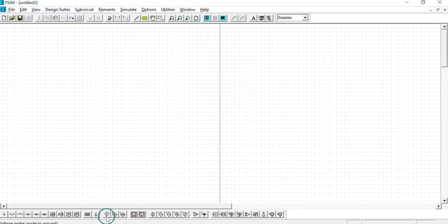and at the top we are having file, edit, view toolbars to work on things. So now I am going to try to simulate the same thing. For that I require a DC source. So I am clicking the DC source, taking it and placing it. And then I require 4 resistors. So resistor is here. So I am taking 4 resistances and fixing them in the appropriate places. When you right click, the direction of the resistance will change. So I am just formulating the circuit.